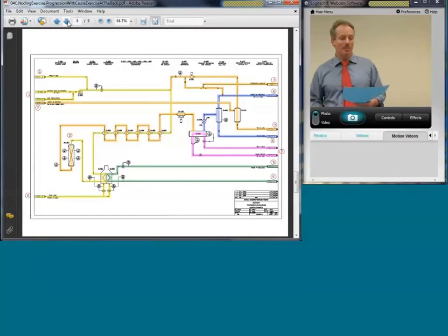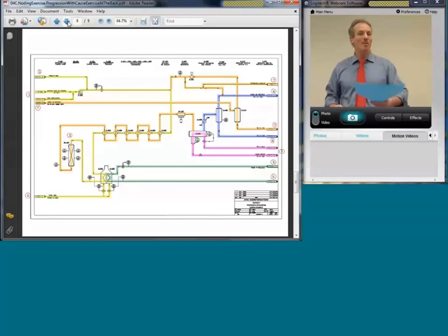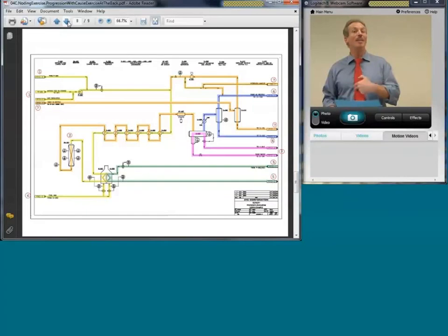It also allows you to focus as the facilitator, constantly seeing the big picture so that you can guide the team. As a reminder, the HAZOP facilitator has to be talking about what you just discussed with the scribe sometimes, or making sure the documentation's in tune, discussing things with the team, and also thinking ahead so you can properly lead or guide the team and facilitate that HAZOP study. Understanding the process and really keeping track of where you are with the process flow diagram is very helpful. Whenever I'm facilitating a HAZOP study, I'll usually have both pre-noted right in front of me so I can keep track of where I am and where I'm going.